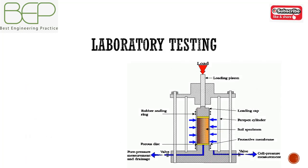Laboratory testing for strength properties is usually carried out in the triaxial test. Tests can be carried out either drained, where a drainage vent is left open to a fixed water pressure during shear, which must be carried out slowly enough to allow excess pore pressure set up by deviatoric stress increase to drain.